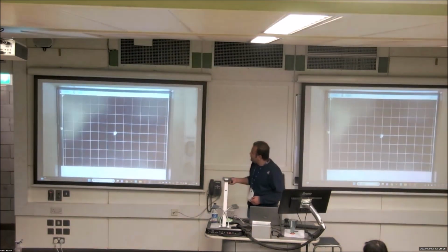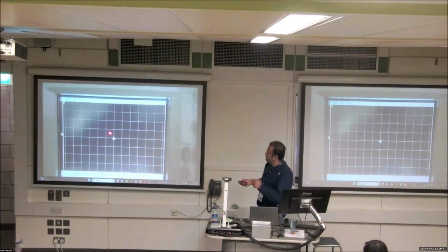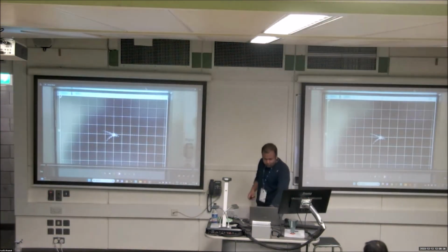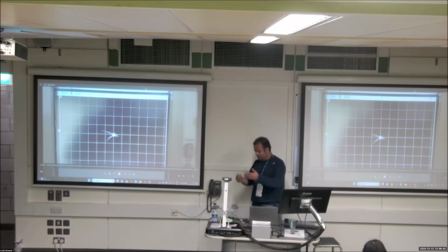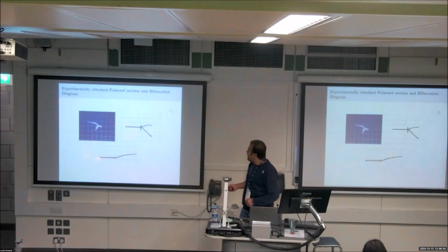So you will find that the narrowband chaos will occur in the way that Professor Banerjee was telling: the stable fixed point, although it remains stable, its basin of attraction becomes 0, so there will be a jump in the state space. That's why you are getting this kind of finger structure. So we have obtained this phenomenon in an experimental electronic circuit, and we have also verified the condition under which there will be no narrowband chaos.